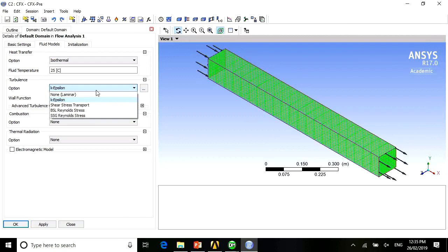I will describe some of the features of these models and also give you a basic knowledge of why certain models are better than others. If you have a targeted problem to resolve certain parts of the flow, you use this model. If not, you can always adopt the standard model, which is nominally K epsilon.